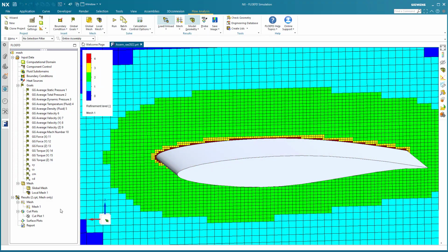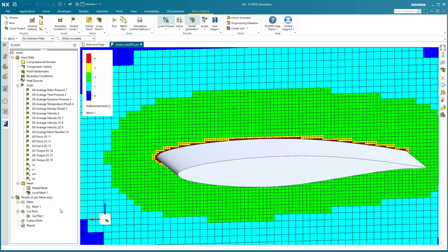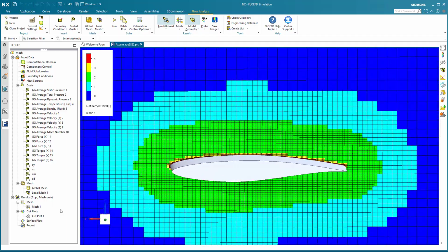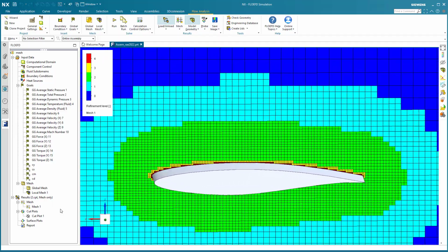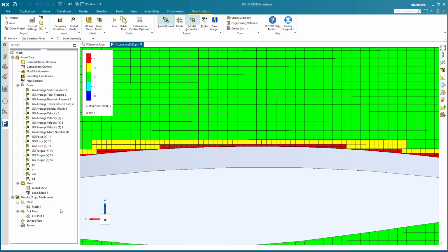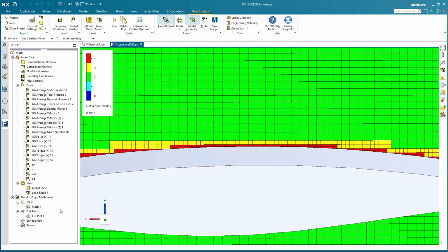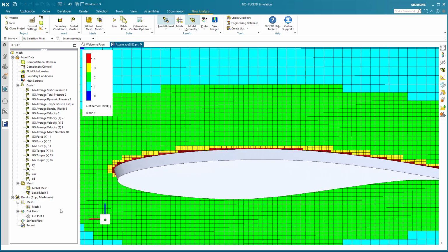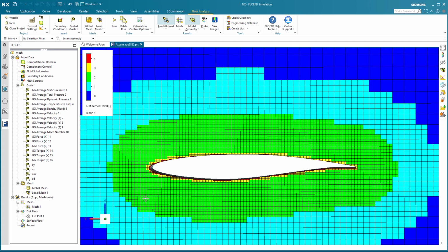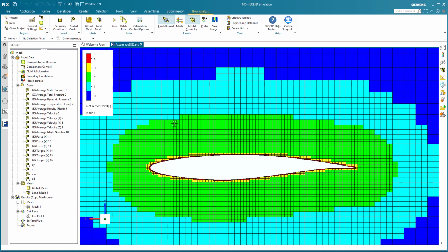Let's now have a look at the mesh created. The first is the default mesh using the base settings, plus our local initial mesh, and has approximately 46,000 cells. The mesh system in Simcenter FLOEFD works using levels, which are shown here colored from blue to red. The base mesh is referred to as level 0 octree. Mesh refining means that a single cell is then split into 8 cells to go to the next level up.